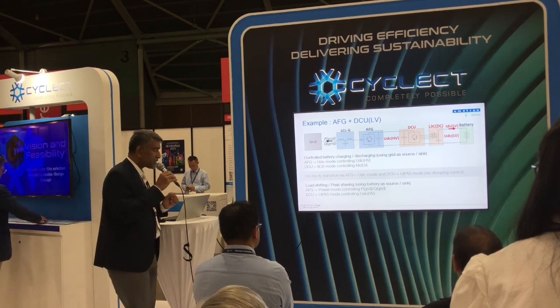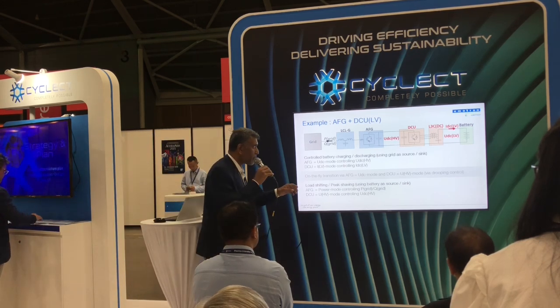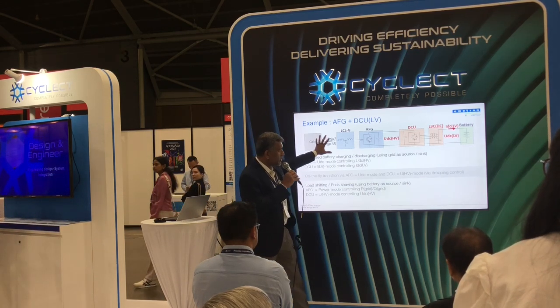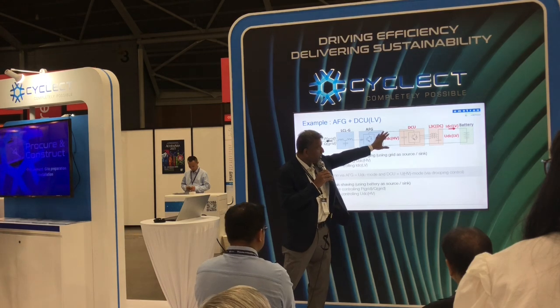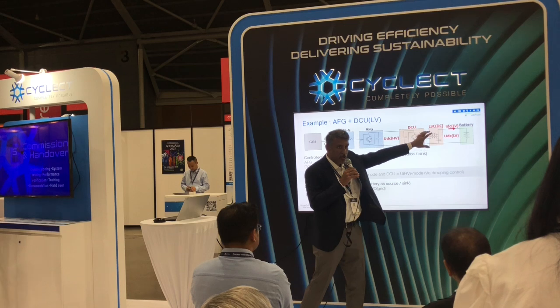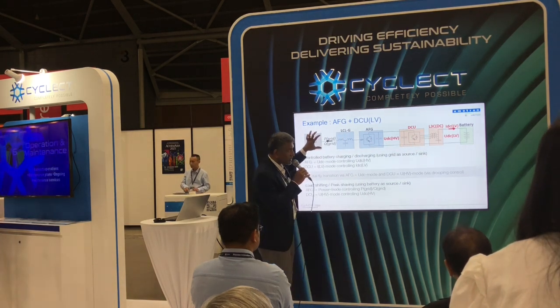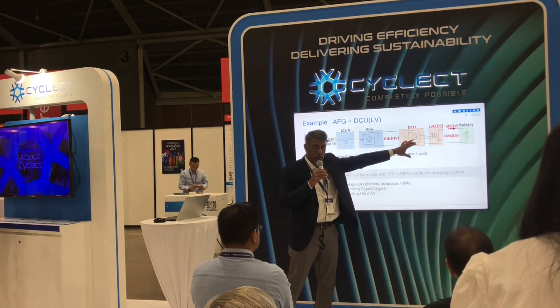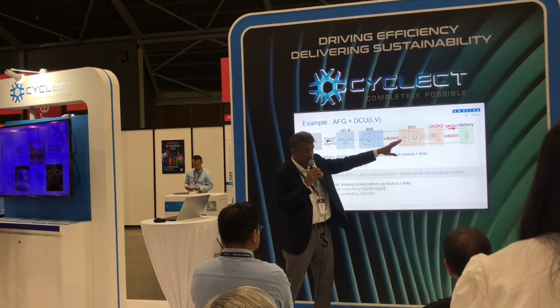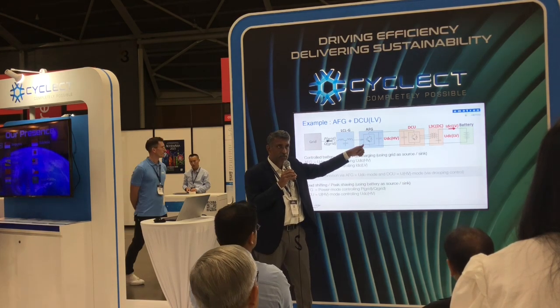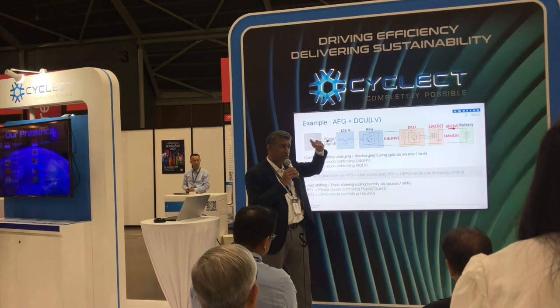So this is a typical case. So what you do is, when you have a normal supply, when the power supply is available, the grid generates a DC voltage. Now in this case, I'm calling this a higher voltage and the battery is at a lower voltage. So when you have a grid supply, I'm generating a higher voltage DC. I step it down to a lower voltage DC, give it to the batteries, but at this time I'm charging the batteries. So you know that when you charge the batteries, there is a certain amount of control to be done.